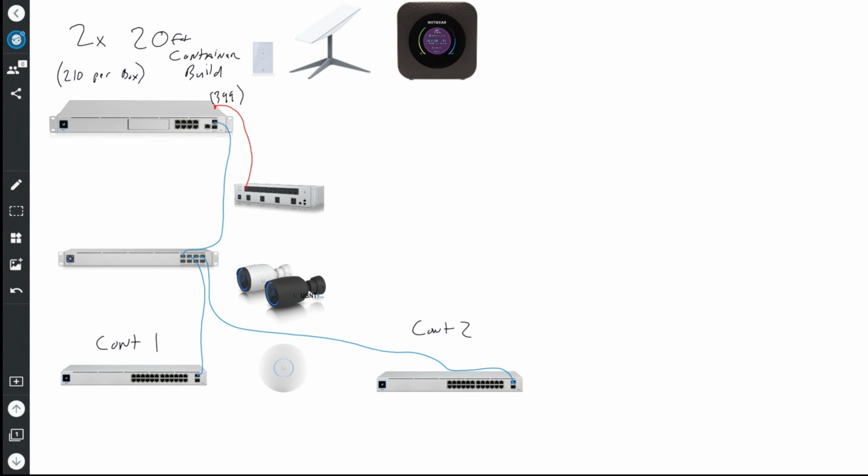Right there. So normally you'll use quarter, there's a 3/4 PVC between the containers. We bury that, and then for that fiber line, you can get the 30 meter. So this would be a 30 meter connection from point to point. You can get that right from Ubiquiti, again, links down below, and you can take that straight over to that machine. So essentially you get a little over 90 feet, or right at 90 feet, for that.